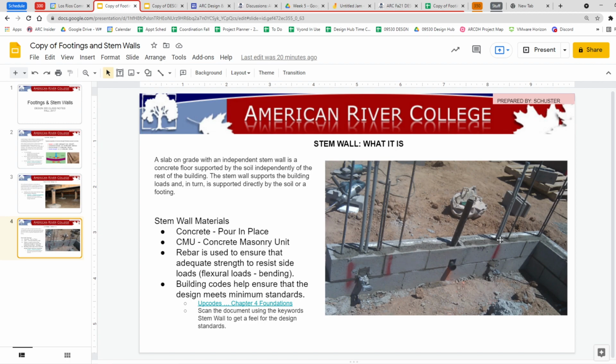So people do different things with the hollow part of it, but it's a very strong construction because you can see that this might want to crack at this joint here, but then it's going to run into the thing. And cracks don't generally like to turn 90-degree angles and run. And it also lets you put piping through it very easily. So if you need to get piping from the ground, above ground, or from an interior up or down, this is a really great way to be able to do it. Okay? And then you just make a little knockout and you still have your full structure.